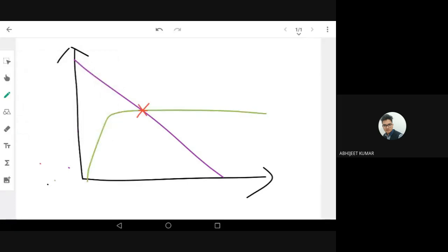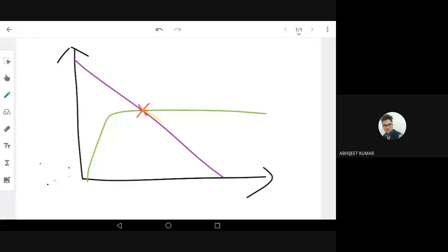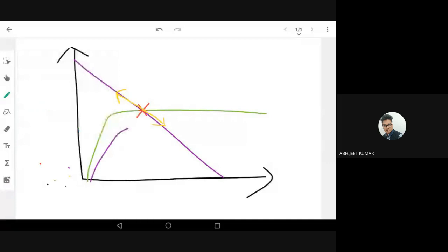By some problem, if my load line is going to change to here, or my operating point is going to change here or here, it is not good. So if there is a mechanism by which I can automatically shift my load line, so that my transistor amplifier operation is not affected much. A feedback mechanism based on output variation, where my VC or IC vary, I'm automatically able to adjust the RC. And if the load line is going to shift, what is the meaning of this? That means the load line is coming here. In case the load line comes here, now on the characteristics, what's happening?